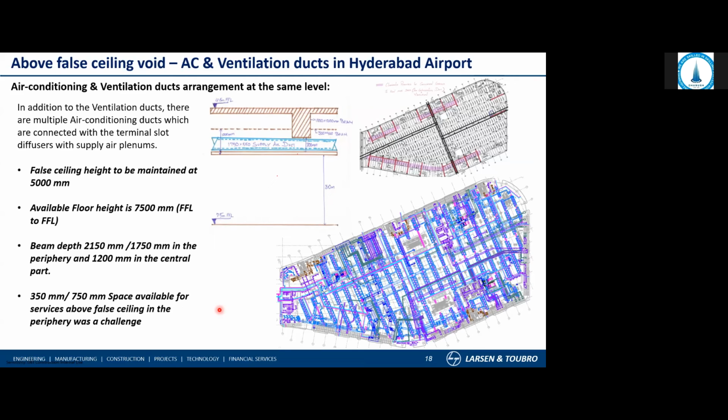But one thing I'd like to tell here: while doing the duct design, architects should know one important factor. Normally they propose that you reduce the height of the duct as much as possible. But the problem is we cannot reduce the duct height as we want, because there is a method to follow in the ducting design, which is the aspect ratio. We cannot go beyond 1:4. So if the duct height is 1 meter, we cannot go beyond 4 meters of duct width. Likewise, if it is 4 meters, we cannot go beyond 1 meter.